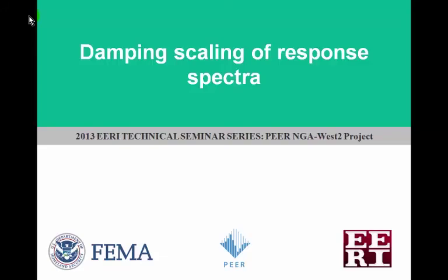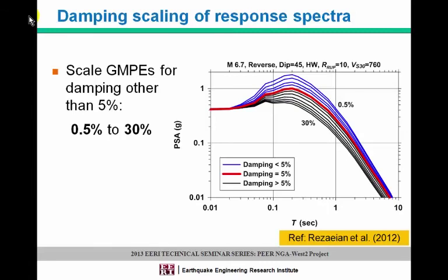So I talked about horizontal ground motion. I talked about vertical ground motion. Everything so far was about 5% damping. 5% damping is only a reference. Depending on the level of input motion and the structural system and so on, it can easily deviate from 5%. Professor Mahin did testing of single-family homes a while ago on the shake table at Richmond Field Station. Depending on the level of input motion, it can be 7 to 13% damping. So 5% really is just a reference number.